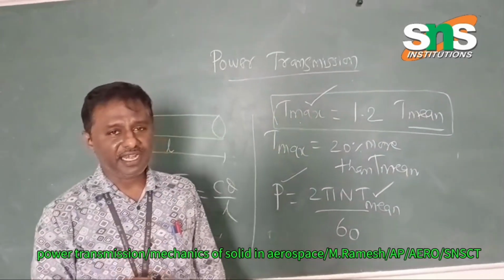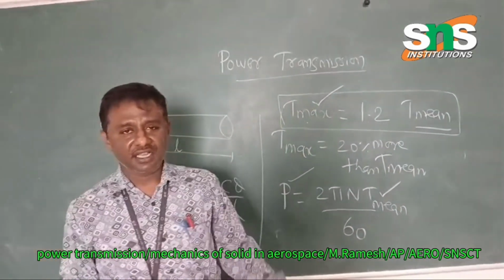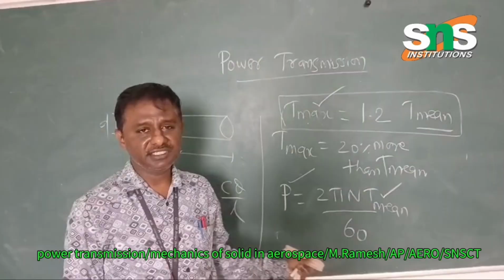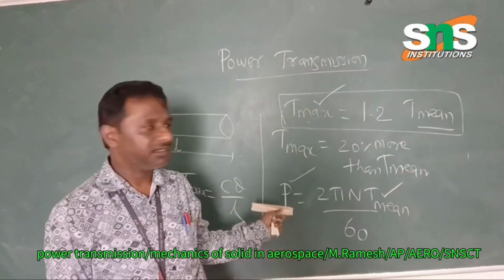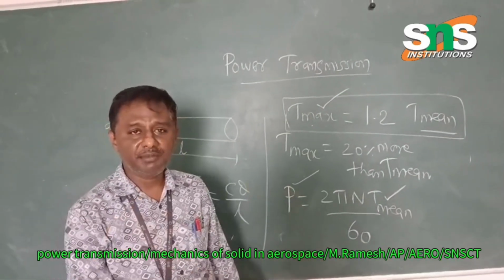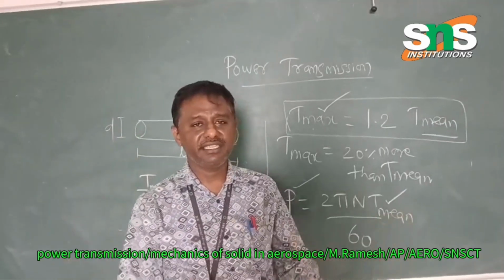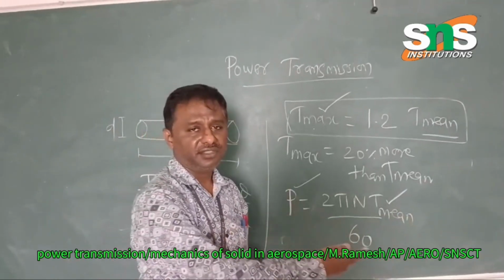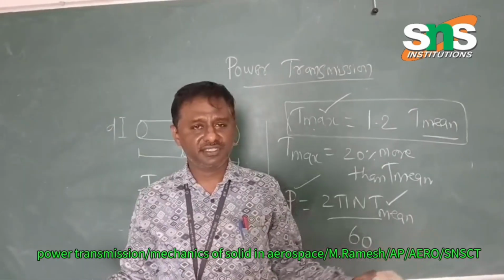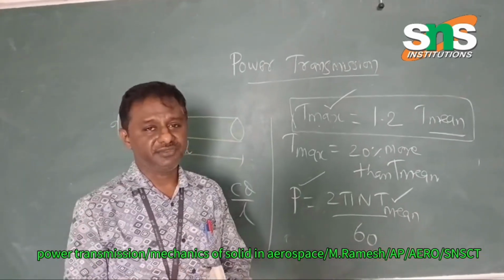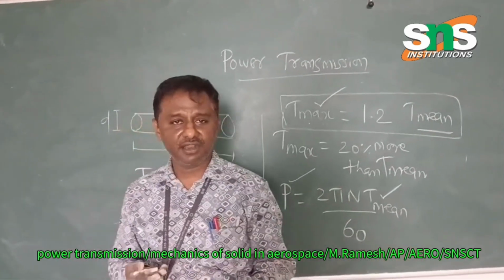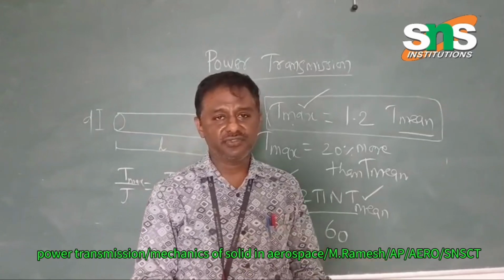Okay, you will have another topic in this. Otherwise, you can solve a problem in this torsion equation or power transmission equation to find the diameter of the solid shaft as well as the hollow shaft. Then compare the hollow shaft and the solid shaft. Which one is beneficial or efficient, whether hollow shaft or solid shaft?